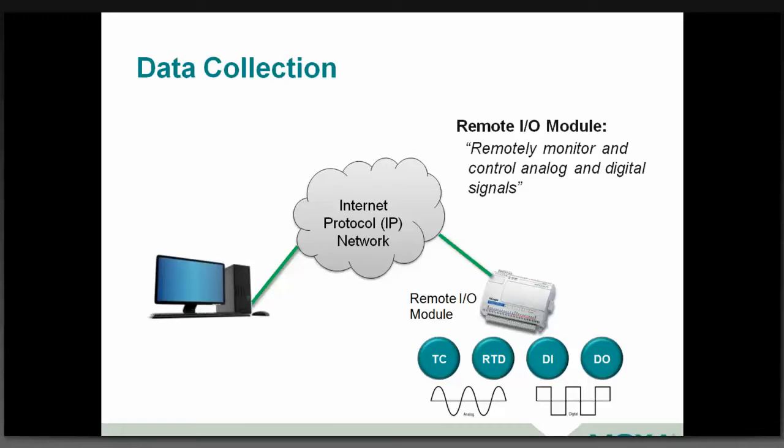When I say analog signal, I mean maybe a 0 to 10 volt signal, or 4 to 20 milliamp signal coming from some process instrumentation, or maybe something as simple as a thermocouple for sensing temperature, or an RTD. It's really easy to put a small little module in place nearby and utilize that remote I/O module to bring that across your network.